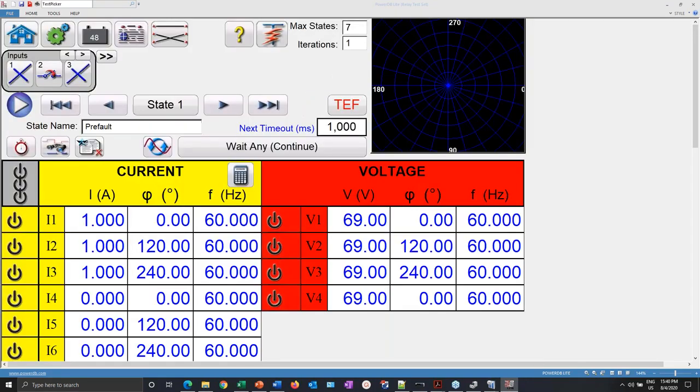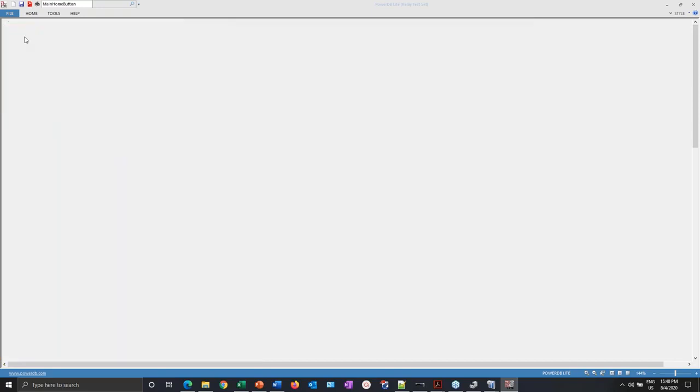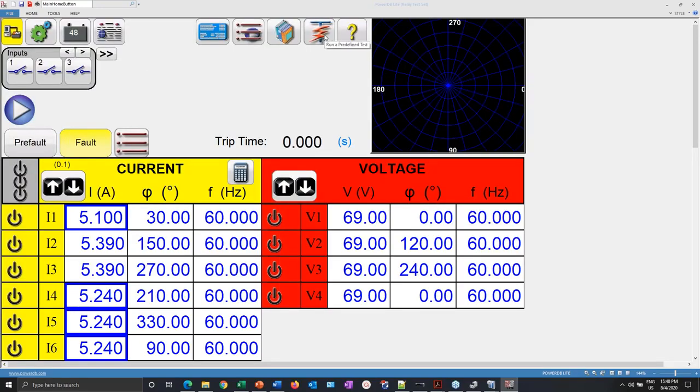Remember that we have a very powerful sequencer tool that you can use to create different states, and especially since you have 4 voltages, you can connect 3 voltages to one side of the relay, the 4th voltage to the VS, and create the different states right here.